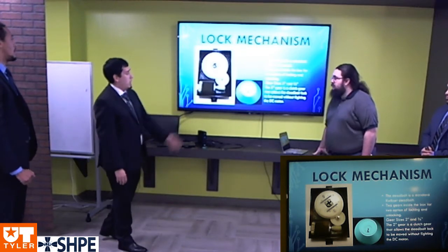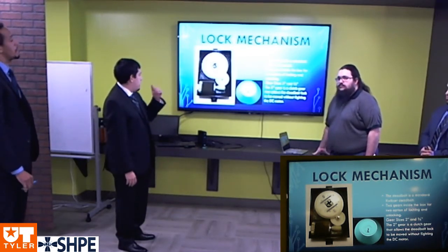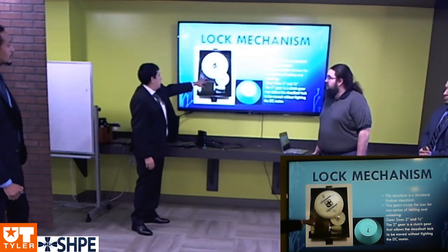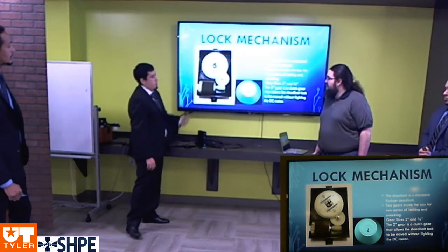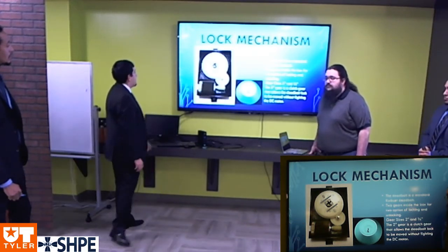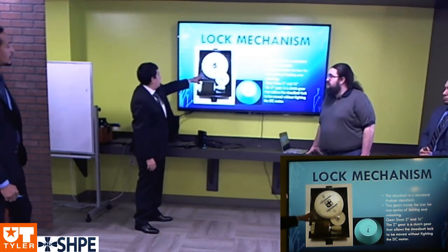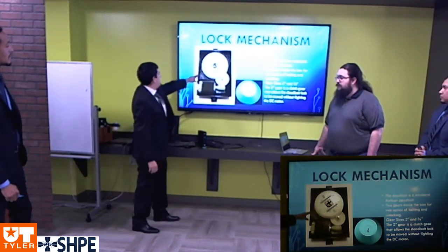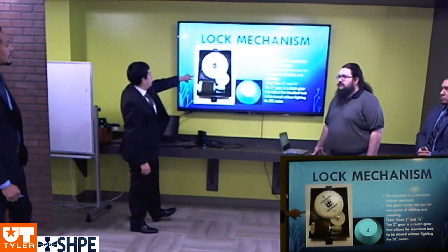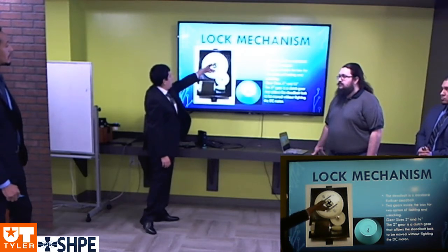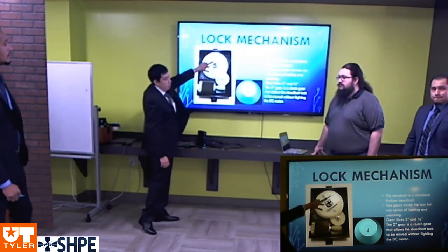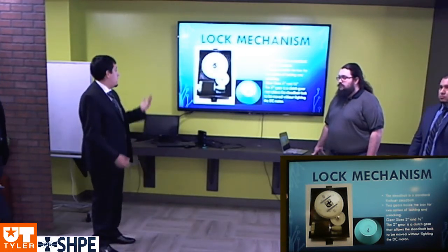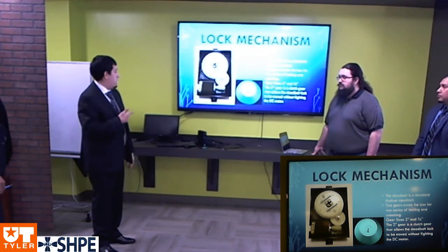So we still allowed key access, and so that was a little difficult to maneuver because if you look at this gear, we didn't want the gear to start moving the motor, which was hard to do anyway. So what we ended up doing was using the clutch gear, which allows movement here without moving the motor. And it has 2 little pins inside that will lock into each other. So when the motor does move, it will move a certain amount and then lock into it, and will eventually turn everything in there. So it allows both the key to be used and the motor to do it on its own.